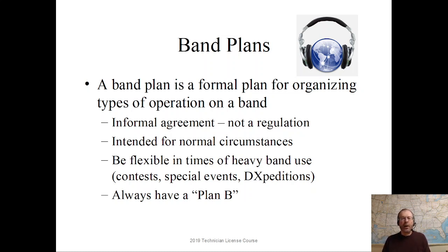So we know that certain frequencies are calling frequencies, like 146.52 megahertz on the VHF band, and that's usually a frequency where we use FM voice. So on a radio like this, I would get on 146.52, and that would be a local calling frequency. It's not usually used for repeaters, so that would be set forth in the band plan as a calling frequency. Now I want you to remember 146.52 because that question could be on your test.